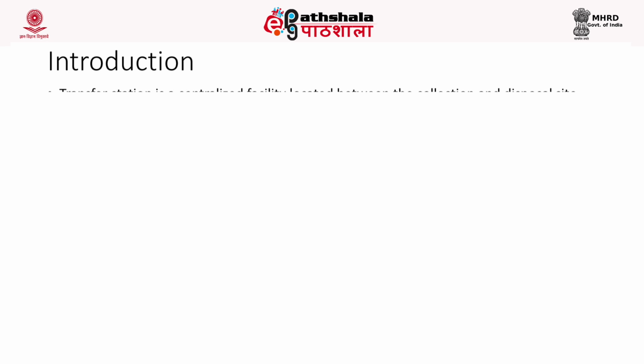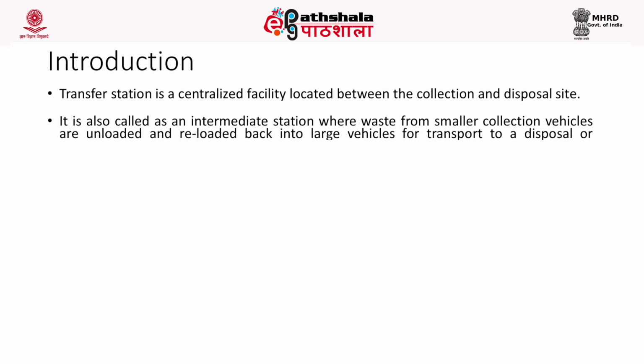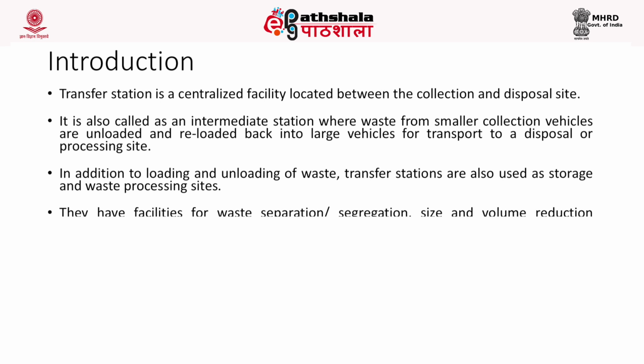Now, as I told you earlier, a transfer station is a centralized facility and it is located between the collection and the disposal site. It's an intermediate station where the small collection vehicles which collect the waste from different sources are brought to this station, unloaded and reloaded back into large vehicles for transport to a disposal or a processing site.